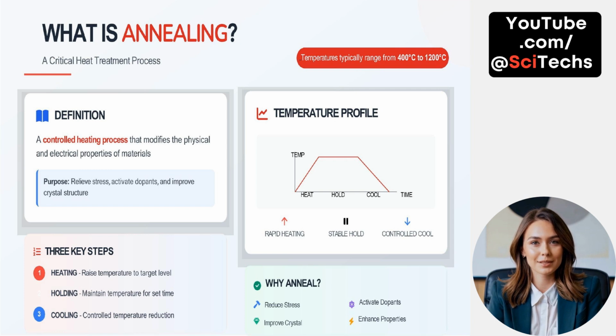This heat treatment typically involves heating materials to a specific temperature range, usually between 400 degrees Celsius and 1200 degrees Celsius, followed by holding and cooling. The main purpose is to relieve internal stresses, activate dopants introduced during implantation, and improve the overall crystal structure of the material. The annealing process includes three key steps.